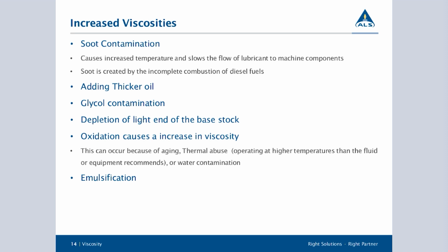But that cloudiness can be an indication of emulsification. It can also be an indication of a few other things. So I don't want you to look at your oil and say, oh my goodness, it's cloudy, it means that it's emulsified. You definitely want to get that oil tested to see what's going on there.